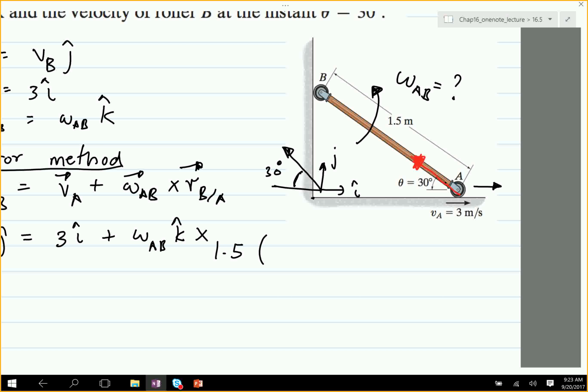So the direction is going to be, if I resolve this vector in the x direction, cosine of 30, but that arrow is pointing in the negative i direction, so it's minus cosine 30. And then to find the j component, it's going to be sine of 30, and it points upwards, and upward direction is positive. So plus sine 30 degrees j. Is that clear? This is very crucial, you get the direction right, because your answers will not have the right sign if you do not get the directions figured out properly.